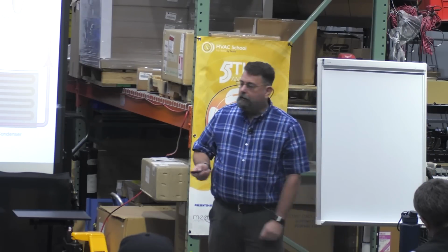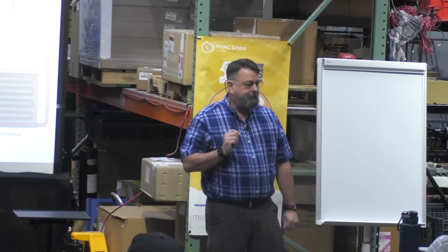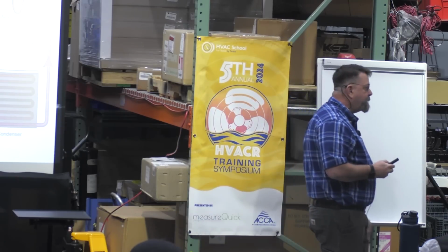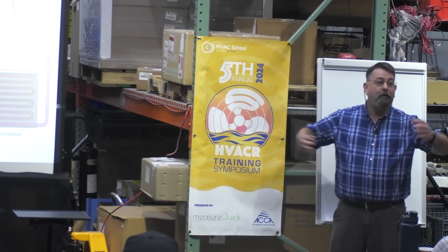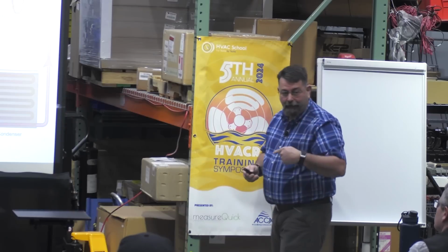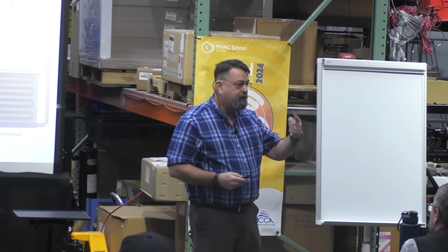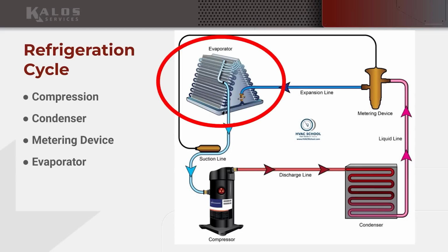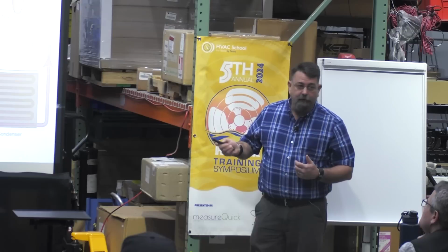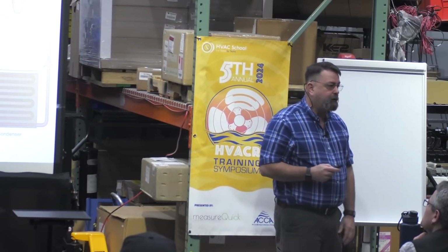All right. Another piece about that: because my airflow is not all over the place, it's a very defined, very small space, and I'm recirculating the same amount of air, I can also predict very precisely how many degrees different there is between my boiling temperature and the air coming out of that supply grill.